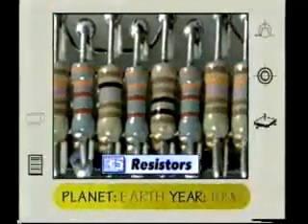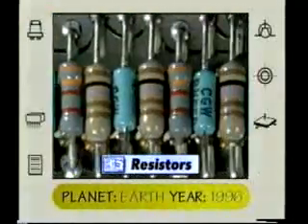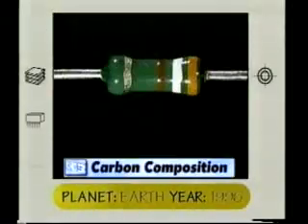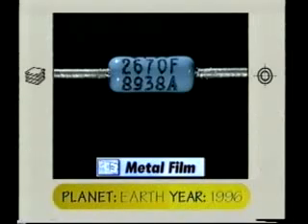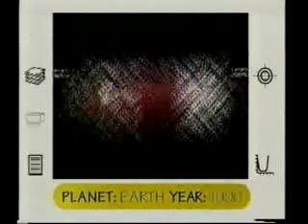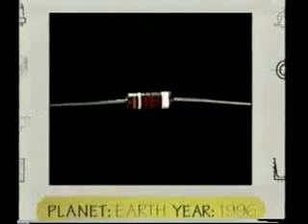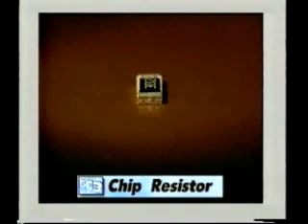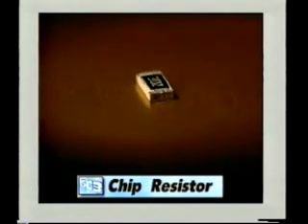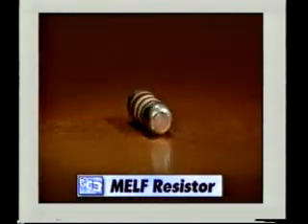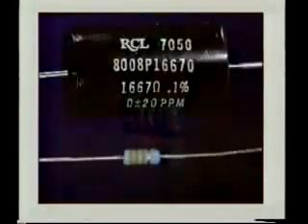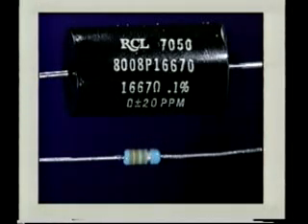Resistors limit the electrical current in a circuit. They are made of a variety of materials, including carbon composition, metal or carbon film, or metal oxide. Through-hole resistors are usually cylinders with 2 axial leads for through-hole mounting, while surface mount resistors are either chip-style or cylinders. Fixed resistors don't have polarity. The size of a resistor grows as its wattage rating increases.